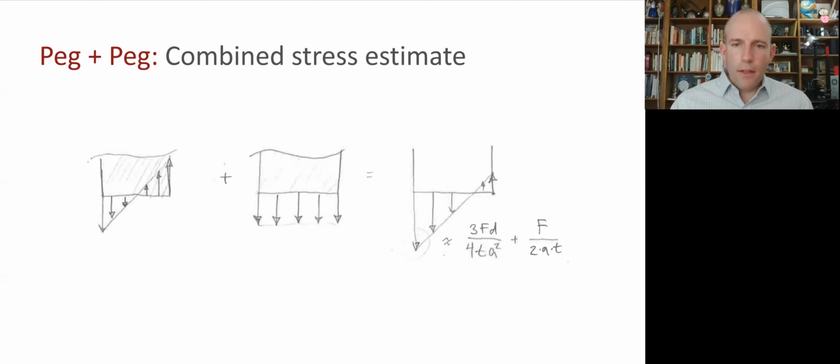So you can see that if we really deeply contemplate the finite element analysis results, that will allow us to improve our simple models, which will allow us to perform analytical optimization. We could solve for A or T in this case. But perhaps more importantly, this process improves our intuition. So we understand why we're seeing these patterns of stress and what phenomena underlie them. And that will make us much better at tuning the qualitative shape or the parameter values as we improve our design and make it more mass efficient. So that's several ways that we can use finite element analysis in a mass efficient design process.